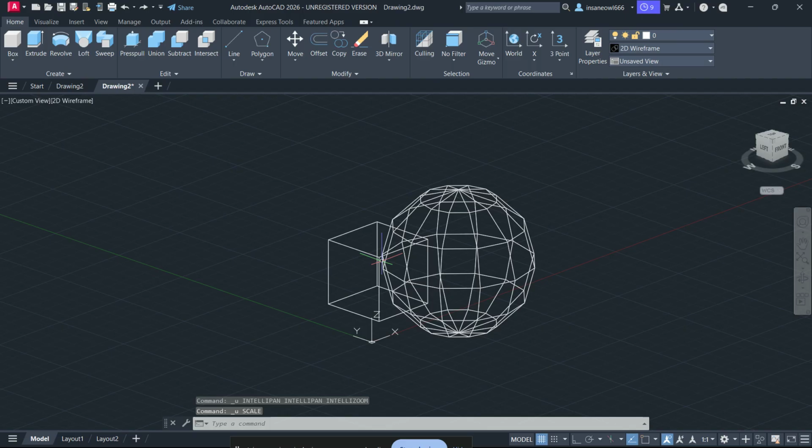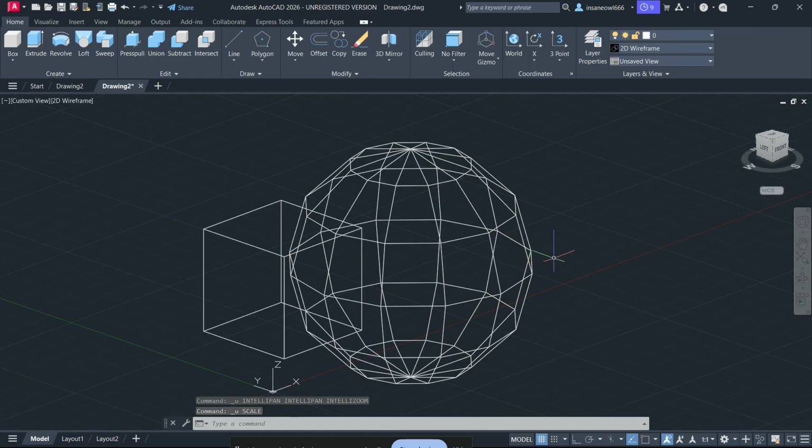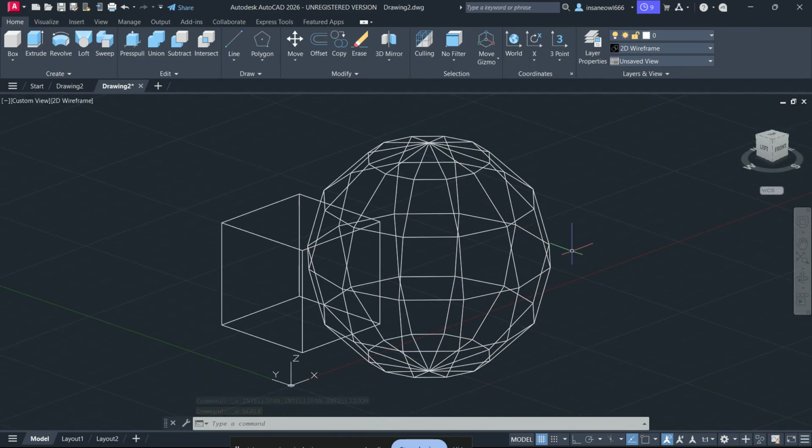So, to recap, if AutoCAD error code 75015 appears, start by reducing the radius, then clean the body, check the solid for validity, change the order of the fillet or chamfer operations, use the chain option, and if needed, scale the model up and back down. In most cases, one of these methods will resolve the issue and let you continue working without rebuilding everything from scratch.